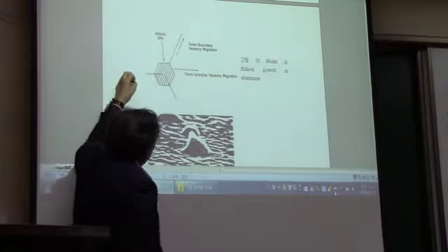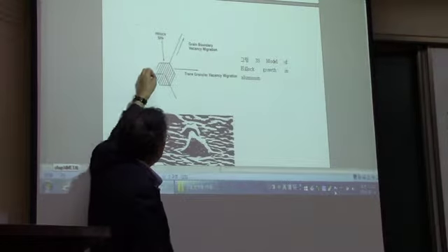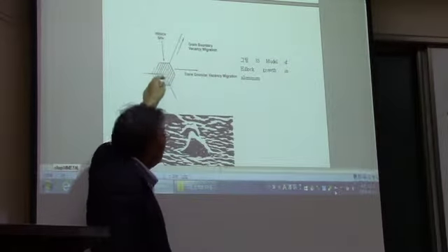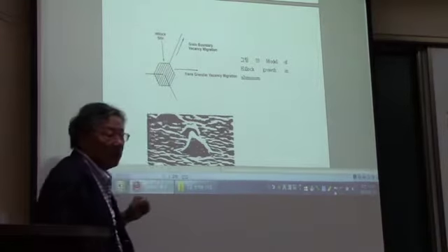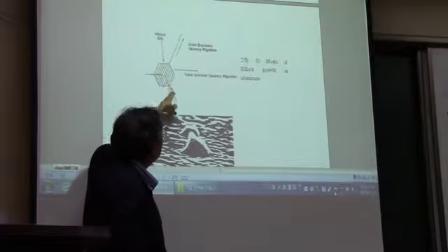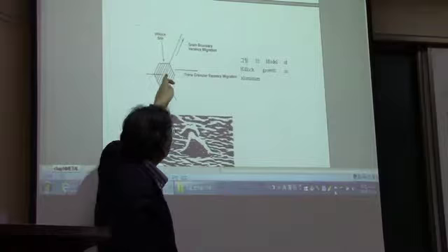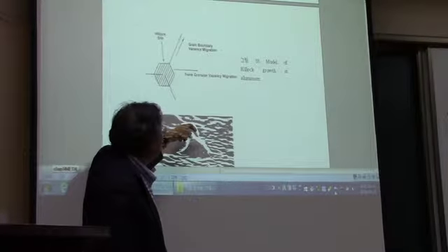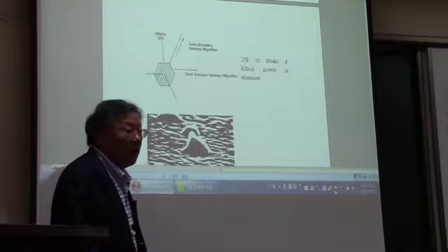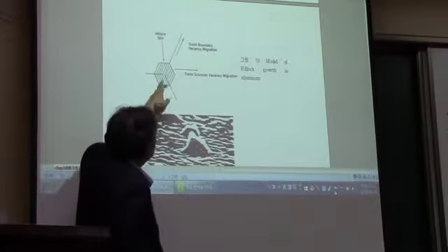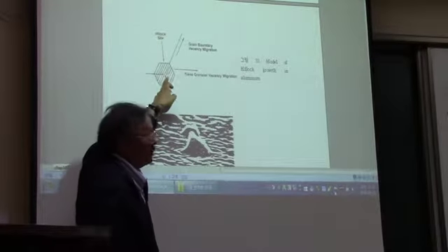So the metal atoms, usually impurities or whatever, travel and migrate fast along the grain boundaries. And if you have a triple point like this, and the metal atoms are moving from here to these two places, then you're going to have a depletion of metal atoms, because you have two exits where you have just one entrance.